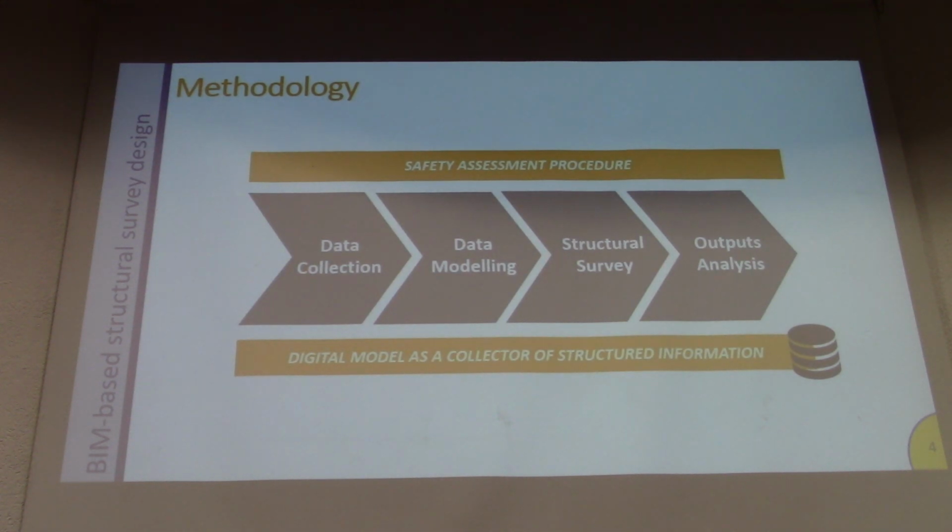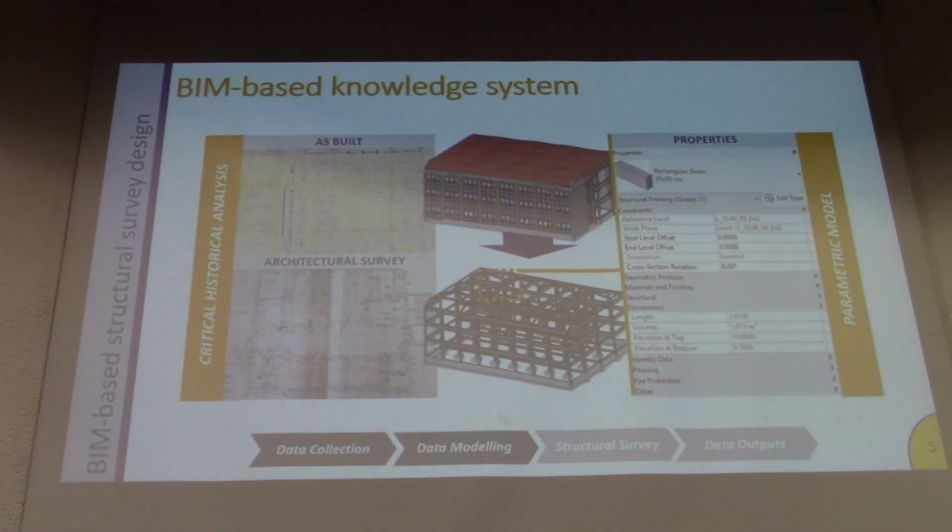So, the investigative methodology aims to enrich the safety assessment procedure as described by the Italian regulation, the ministerial decree, by setting up an as-is model of the building. The digital model is intended as a collector of structural information that can be available for different users and for different purposes, and can be implemented over the time. So the main steps covered are from data collection, data modeling, the structural survey, and the management of the output. The object is to set a BIM-based technology system.